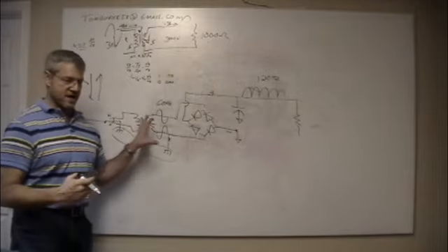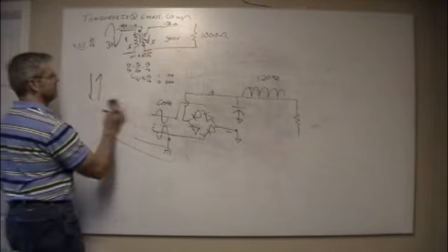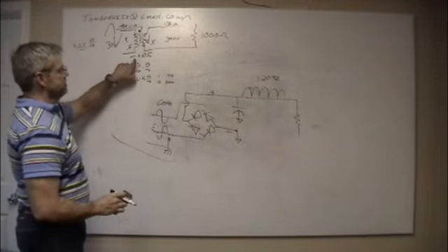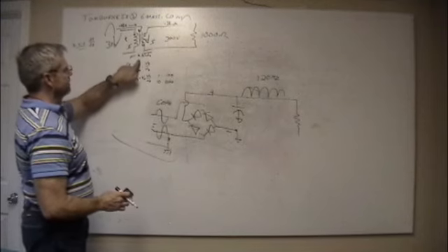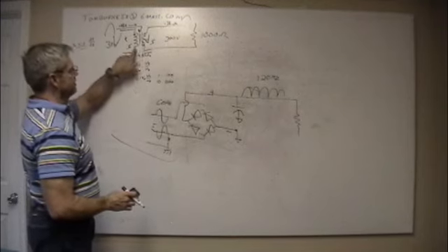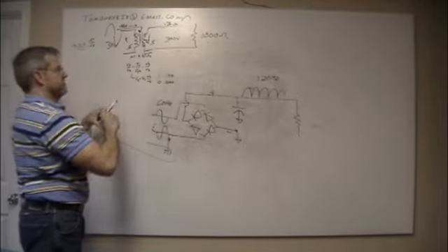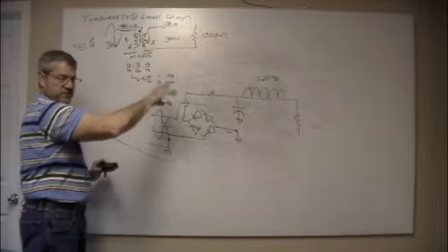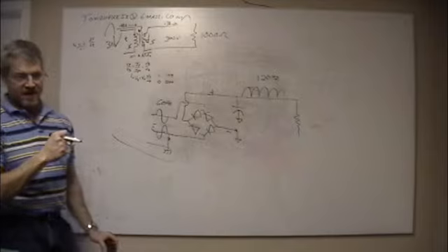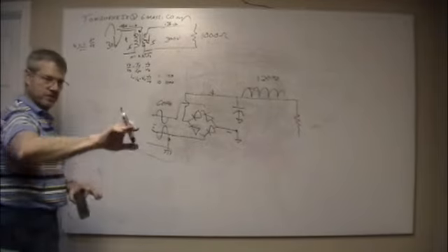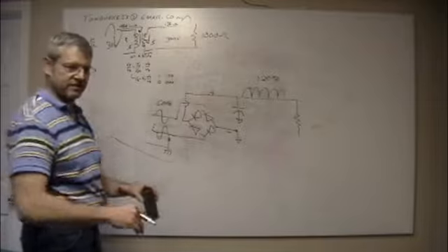Using the transformer as an actual transformer. Now this K is a coupling factor. It's the mutual inductance. If I look at this, it looks like an inductor going through. And you can actually play impedance matching games with a transformer. That's why there are impedance matching transformers on audio circuits. Your mics are usually really high impedance, but what you eventually get to is an 8 ohm impedance out on the speaker, and you have to do some transforms in there.